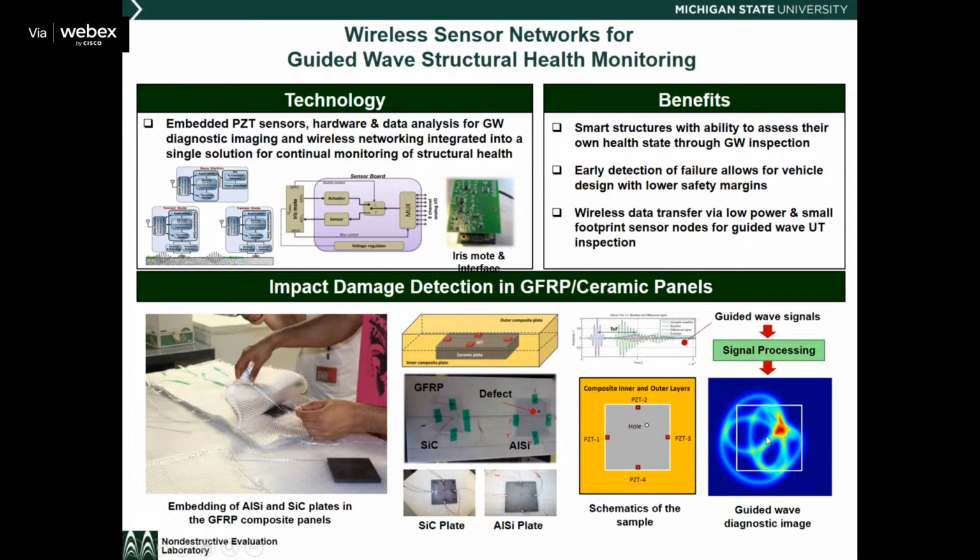Well, if we're doing imaging and signal processing from those guided wave measurements, you can actually try to do imaging. Here, this is called probabilistic diagnostic imaging, where you can find the most probable location of a damage by using this probabilistic imaging technique. I will briefly touch on this in that lecture, on how, for the inversion, we can find this location.